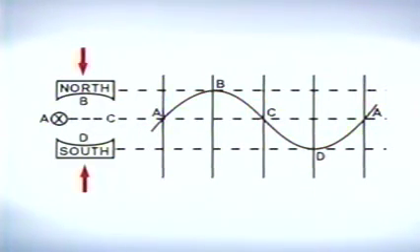The magnetic field is located between the north and south poles of the magnets shown at the left of this diagram. When the conductor X is located in the middle of the magnetic field, namely points A and C, the potential will be 0. As the conductor rotates from point A to point B, or from C to D, the potential increases until its maximum is reached.